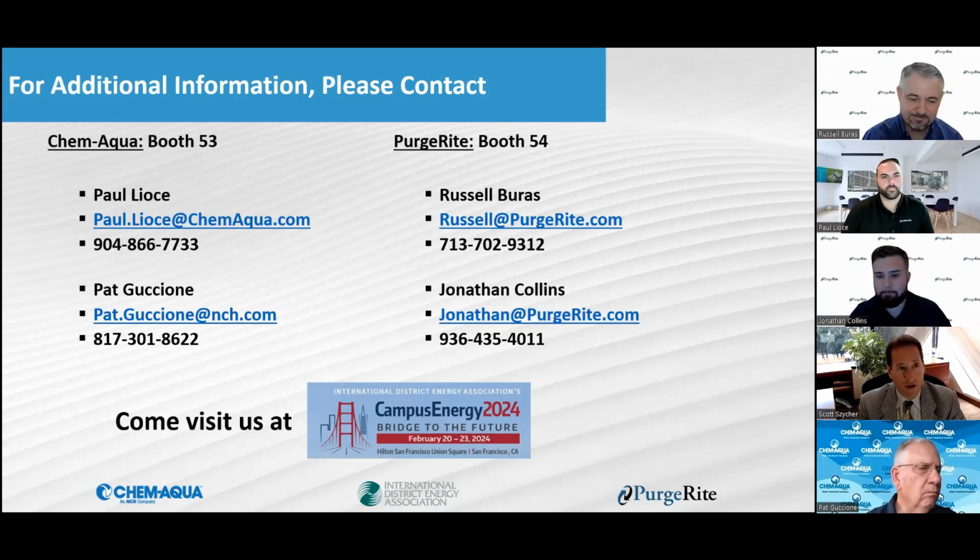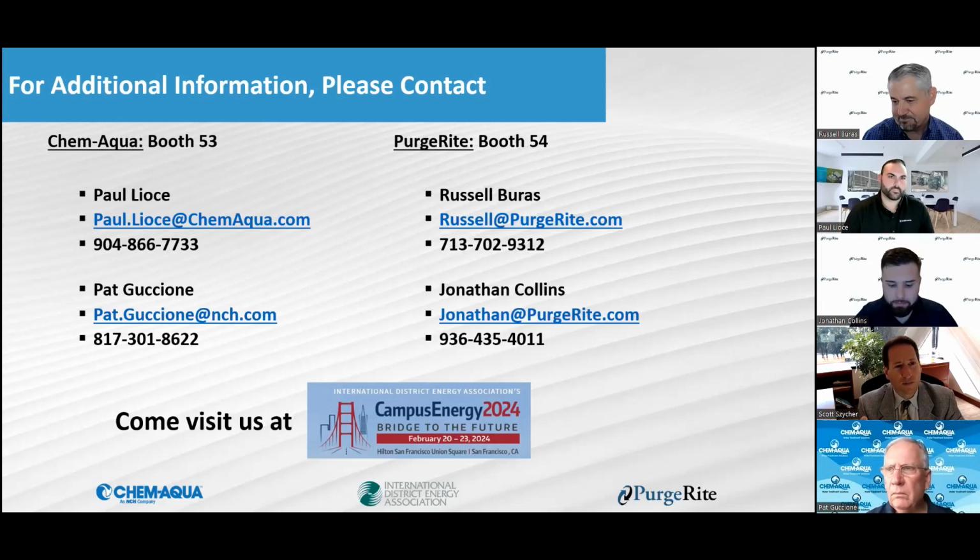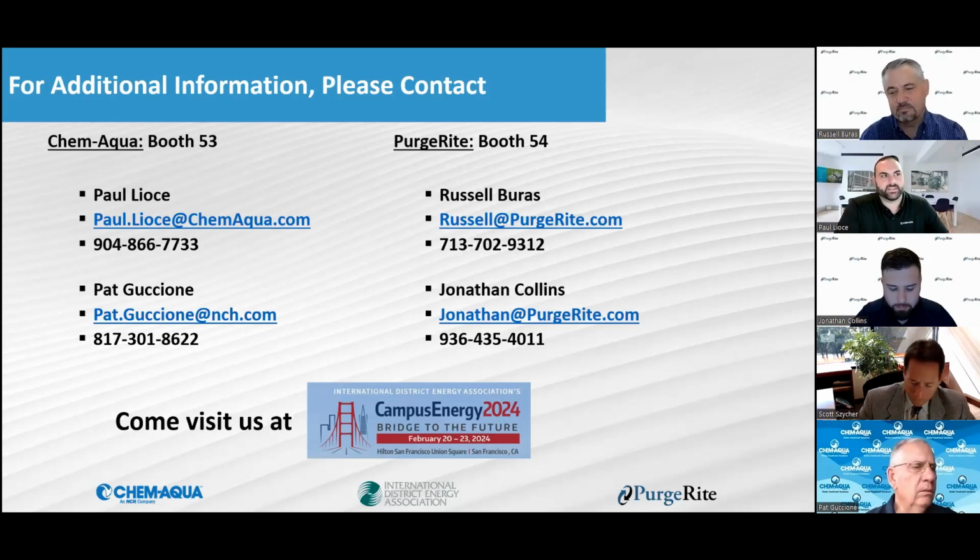I had a question here that I thought was good and wanted to pose to you. For chiller plants with year-round operation, what is the best practice for open loops on standby for extended operational readiness? I think on that one, from a water treatment standpoint, think of it in the sense that every drop of water sees every biocide feed.